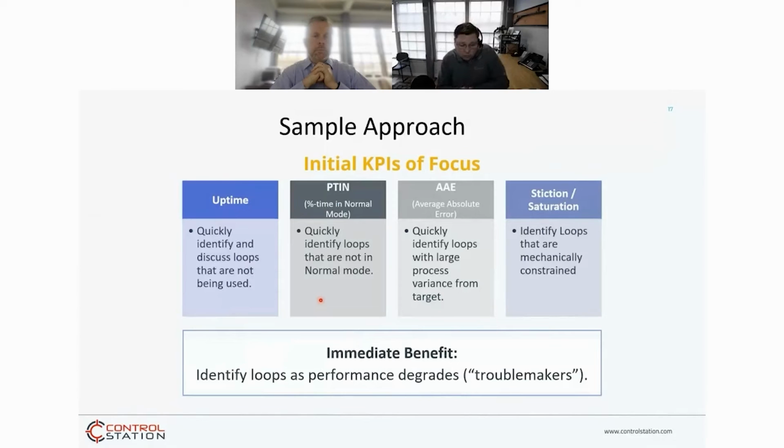You're going to find controllers that are in manual mode because an instrument was supposed to be replaced, a valve is broken, or the operators run it that way. You're going to start putting controllers in automatic and start to quickly realize that there's probably some instrumentation or mechanical issues that have to be corrected. It's a great number to start. And you can really start to track and make some positive changes if you focus on 1, 2, or 3 kind of simple numbers.